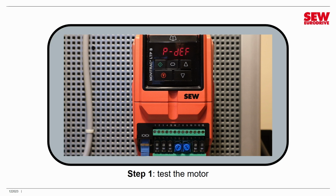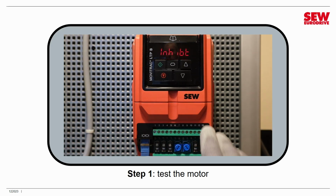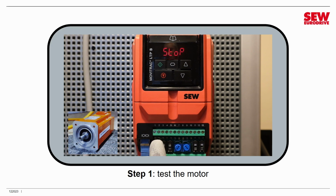Okay, well, our VFD is showing PDEF. That's because we factory defaulted it, so we need to clear that message by pressing stop. So we'll do that, and now we'll take it out of controller inhibit by turning the 2 safe torque off switches on, and we'll enable it by turning digital input 1 on, and we should be ready to run now.